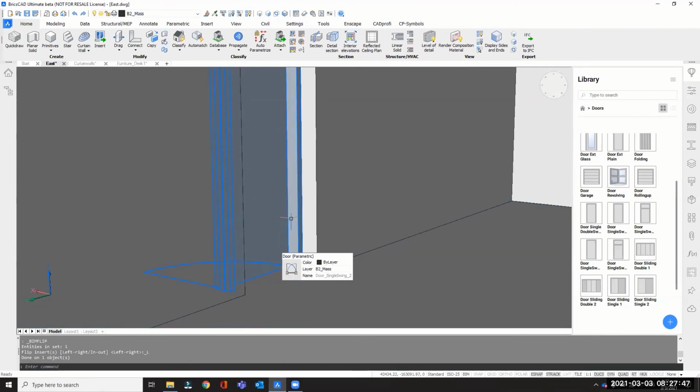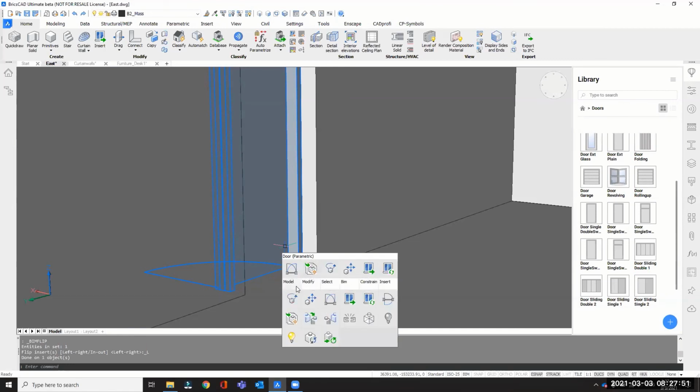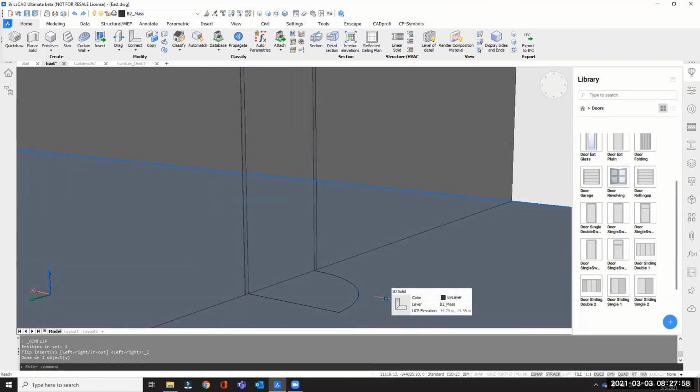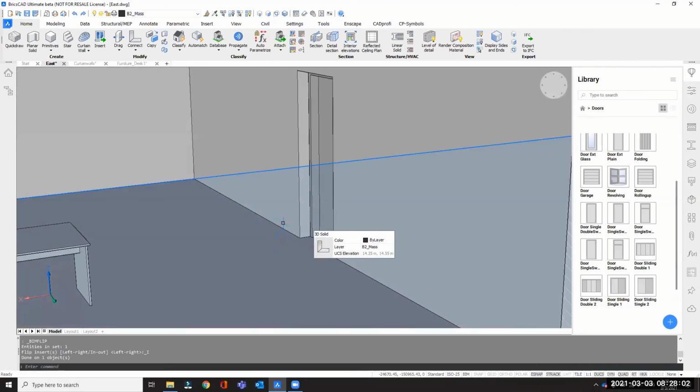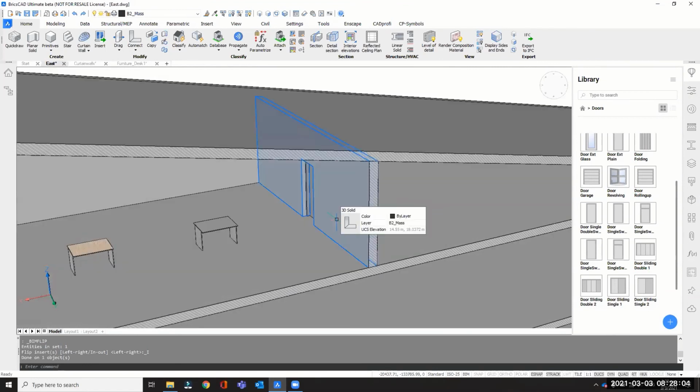And this is another option of flipping the door. We have BIM flip, and we have another BIM flip here, which is where your door opening will be. Now clicking that, it will go to the other side, and now it's inset on this part of my wall. So I think that's pretty good and quick to follow. That should be easy for you to test out properly.